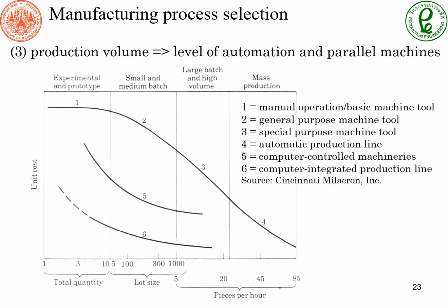As our lot size increases, we will need level 2 general purpose machine tools, which have many standardized toolings. For example, a turning machine with multiple turrets or spindle heads, or a milling machine with multiple spindles. When we start to make products in large numbers, we will need level 3 and 4, which are special purpose machines connected to create an automatic production line. In the graph, you can see that as we increase lot sizes or production rate, shown on the x-axis, we need to increase the level of automation from 1 to 4.